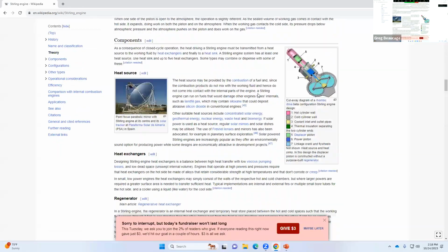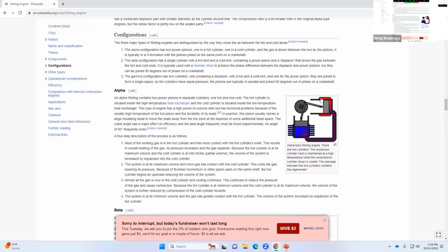Anyways, at the bottom of this, it shows that you have the sunlight focused in with a parabolic reflector on a piston, and that's attached to some kind of generator or alternator. Then there's a cold part hidden from the sun that has a radiator on it. Basically, the heat expands, and with a flywheel situation here, it pushes it back down, and the cold will contract. That's basically a Stirling engine. It's the simplest kind of heat engine, and you can use low level heat with it.